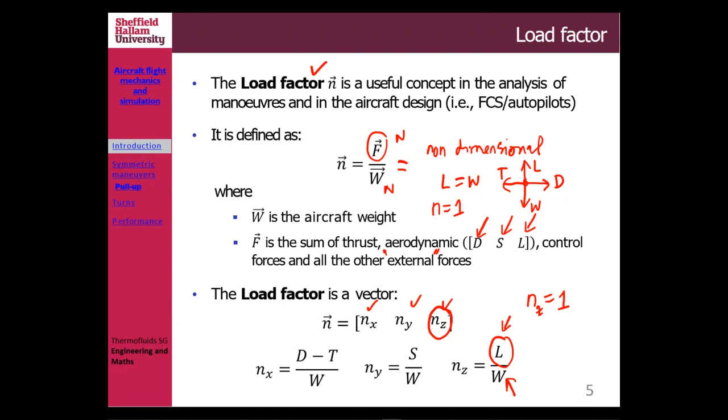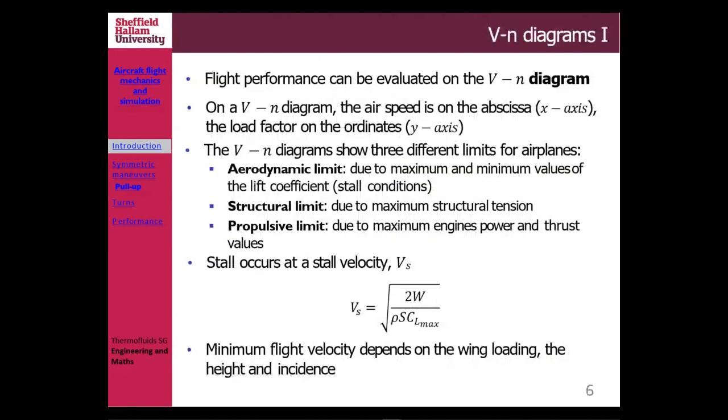If the atmospheric density is different, then sometimes you have a slightly different flight envelope. As an aircraft designer, for the x-axis velocity you usually use equivalent airspeed, which can apply to any atmospheric density. Okay, let's have a look at the next slide.